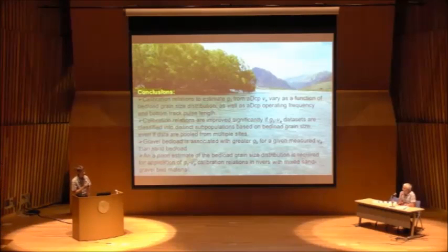Okay, so for the ADCP side, I think if you can get an ADCP into the river during the flood, it would work except for one caveat, which is high turbidity. I've had some occasions with extremely turbid flow where the bottom track doesn't reach the bed and it doesn't work. So it depends on the nature of the flood. But if you're able to traverse the river by some means, either by boat or across a bridge or something like that during a flood, then it should be okay.